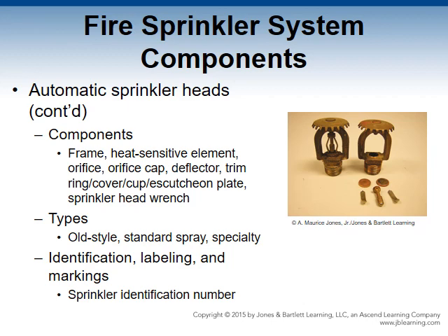Still being produced today, but NFPA 13 limits its use to storage vaults and situations that require unique water distribution patterns. Your standard spray heads emerged in the 1950s and remain the most prominently installed today. They can point in only one direction, and they have several different categories. First, you have the pendant, which points down. You have the upright that points up, and you have the sidewall, which is installed parallel to the ceiling or the floor. The head orientation is critical to the successful installation of a sprinkler system. Placing a head incorrectly will compromise the ability of the head to perform its intended function.